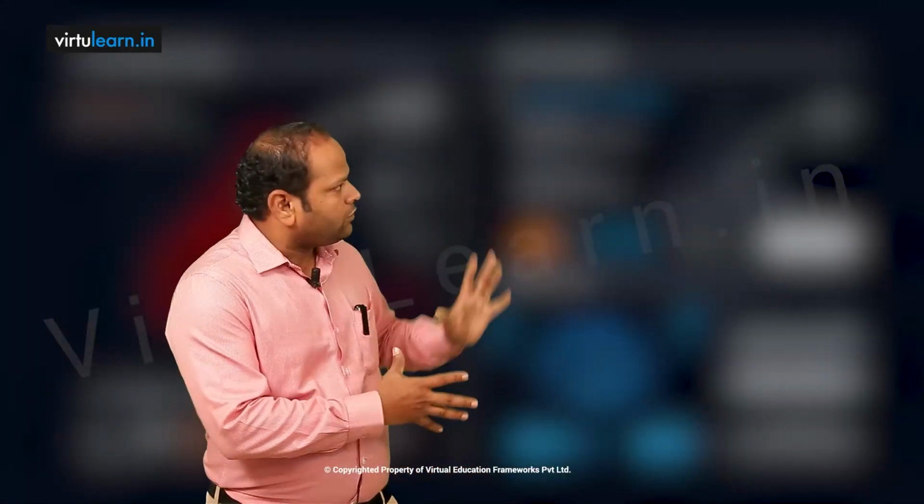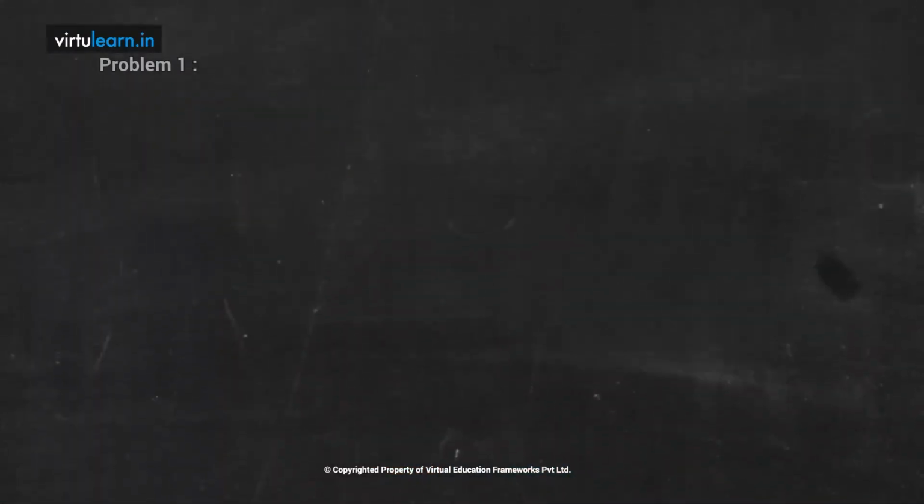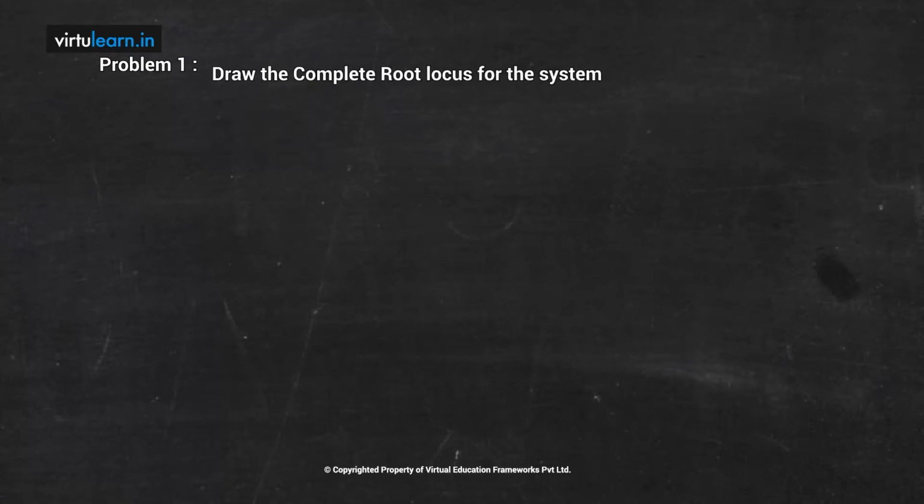So steps are already given, and using the steps we can draw the root locus diagram. We start with problem number 1. Here is the problem statement: draw the complete root locus diagram for the system whose open loop transfer function is given by G(s)H(s) = K / (s(s+5)). This is a very simple problem. Start with a simple problem, and slowly increase the complexity. We need to draw the root locus diagram for this.